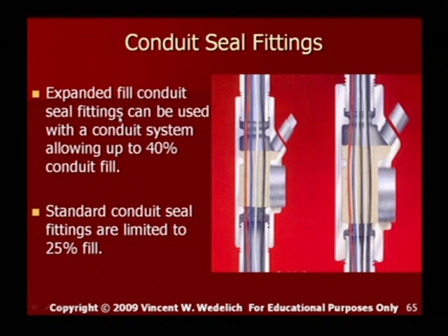Expanded fill conduit seal fittings can be used with a conduit system allowing up to 40% conduit fill. Standard conduit seal fittings are limited to 25% fill. So you're probably thinking, oh my God, do I have this problem in my installation in my plant? And chances are pretty good you do, because a lot of people don't realize this, and you need to make sure you check that. Another thing is these conductors have to be spread apart properly,